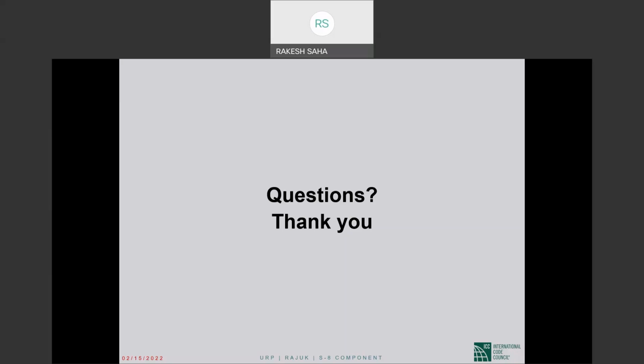So the next question is, between modal analysis and time history analysis, which will give much better or accurate results? Which analysis do you suggest? I actually said this: elastic time history analysis does not give you any more information than modal response spectrum analysis, as far as I'm concerned. You may get more numbers, but no new knowledge of significance.